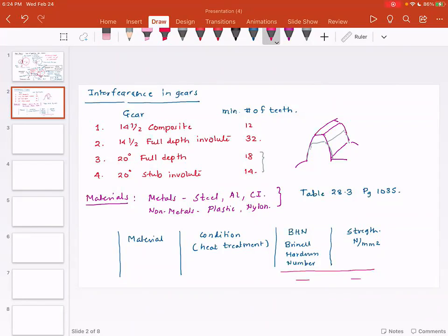So that is something to keep in mind, all the way to alloy steels, which have excellent strength properties and good hardness properties, all the way to chromium molybdenum steel, all the way up to phosphor bronze, case hardened steel. Depending upon the applications, for an example, size, weight, cost, whether we have lubrication available or not, what is the level of heat that needs to be dissipated, you select the appropriate material.